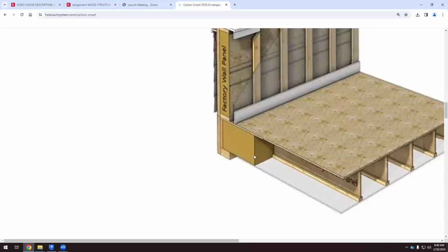In passive house, the main goal is to prevent thermal breaches from happening. So this is an extra thermal insulation between the joists. This doesn't have to be rigid. Rigid insulation works well if it's exposed to the outdoors, but this is indoors. So we have the first layer of thermal insulation here. This can get wet because it's exposed to the outdoors.